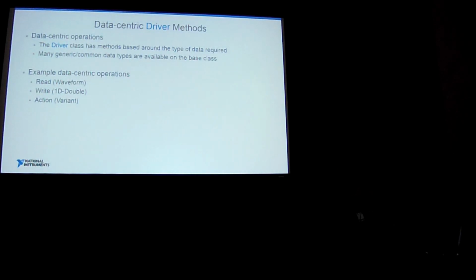The root level driver class has methods around the data type that is being returned or written to or acted on by the driver, by the hardware. Some examples here are read waveform, or write 1D double, or do some action with a variant.